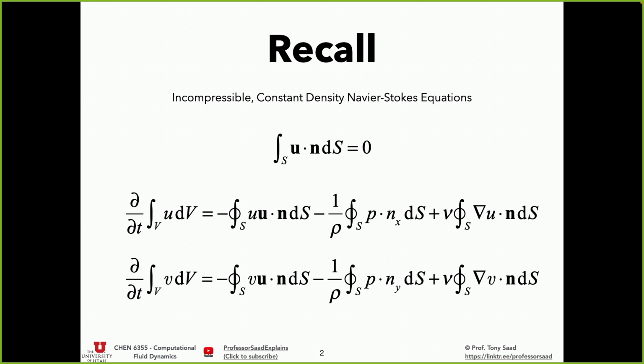And you can reason your way through these convective fluxes. This is the convection of u momentum with the velocity field vector u. Convection of v momentum with the velocity vector field u. Okay, so this has two components as well, right? u and v, x and y components, and same here. These are quantities that go in two directions, right? In 3D, you'll have three dimensions.